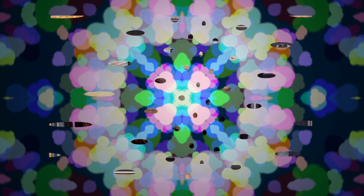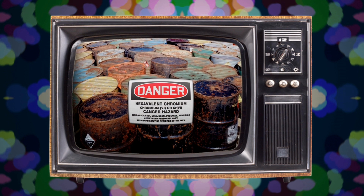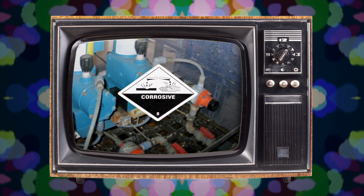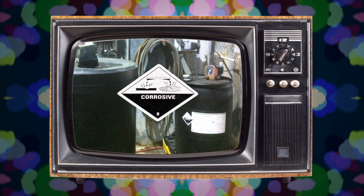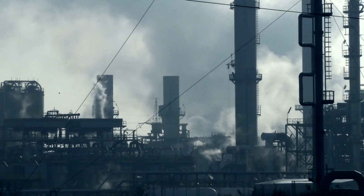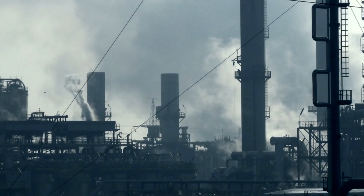In those early years, water treatment was based on chromate chemicals, the dominant method for evaporative cooling systems at the time. These chemicals were typically fed in conjunction with acid to maintain pH in a near neutral range. This treatment approach was very effective at minimizing corrosion and maintaining the galvanized surfaces. However, while effective, chromate-based chemicals were found to have negative environmental and health impacts.